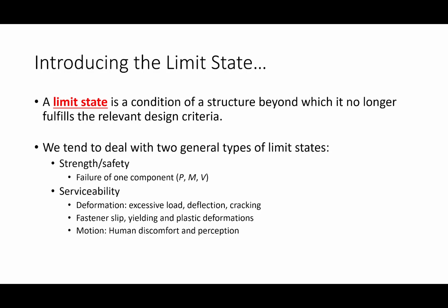So it's possible that you may be designing a beam and you do the math and see, okay, I need an 8-inch deep beam to be safe, but I better use a 10-inch deep beam, because an 8-inch deep beam is not going to be stiff enough to prevent the plaster from cracking. Does that make sense?